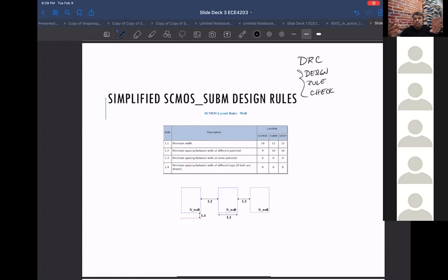You rerun the error checker. It says, okay, you fixed these, but maybe you caused these other errors when you fixed these, or you didn't fix these other ones. Then you do that iterative process. You really need this design rule checker. If you did it just by drawing and sending to the foundry, you're guaranteed never to get the layouts right. But to create that starting drawing, you need to follow the rules and see what they are to get the starting point. But after that, you really rely on this tool.